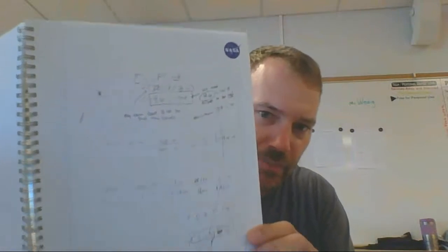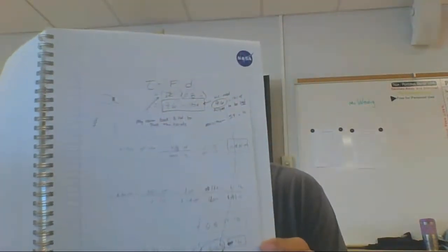Like, how do we figure out how much torque our motors needed to provide? We actually went to each one of those blinds and pulled on them with a force scale to figure out how much force it takes. Okay, so if our gear is 1 inch in diameter, how much torque does it need to create enough force to lift and raise those? So engineering notebooks are for exactly that.